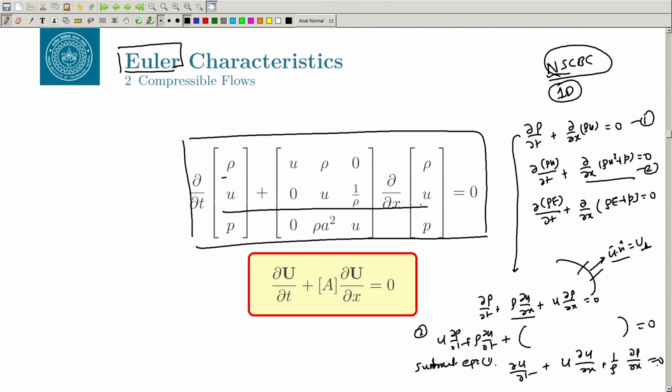Okay. And similarly, for the third equation you have to use E equal to basically kinetic energy, half u squared in 1D, plus CvT, and use the ideal gas equation, and you have to basically use this dρ/dt going to 0, and finally you will get an equation in terms of pressure. So, please go back and work this out. Right now I have written everything in the matrix form. I hope you know how to read this matrix. We have discussed the matrix form earlier.